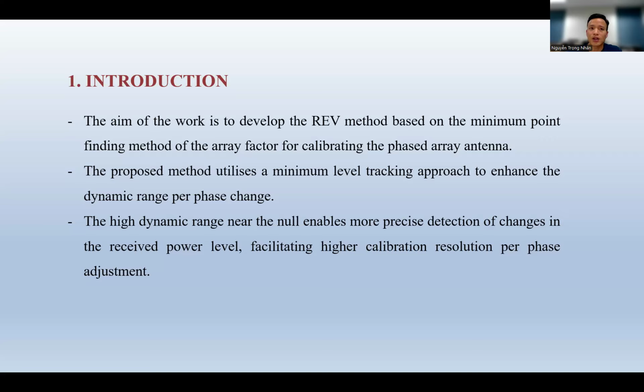Unless real-time on-board calibration is necessary, the calibration method based on a lookup table generated by an initial calibration at manufacturing level might be sufficient. The rotating element electric field vectors method has advantages in terms of accuracy and system complexity.